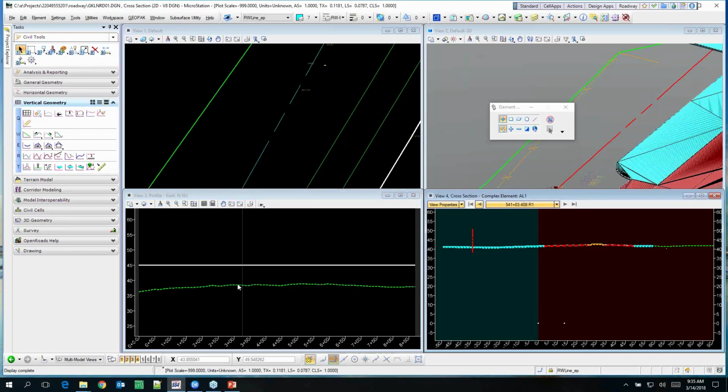Yeah, and we're not going to do that step in here, but that's the next exercise. It's the same concept where if you just have a constant elevation, like say 3 feet underground, because maybe you don't have any more detail, you can just do it this way. And as your feature definition is set to utilities, then it'll plot the utility. As a matter of fact, that's how we display the CL symbol or the center line symbol in cross sections. We take the baseline, we create a profile of existing ground, and then we tell it when you cut through this baseline in 3D, we want you to display a BL symbol, which is labeled where the baseline is in the cross section. Same thing for the proposed center line.